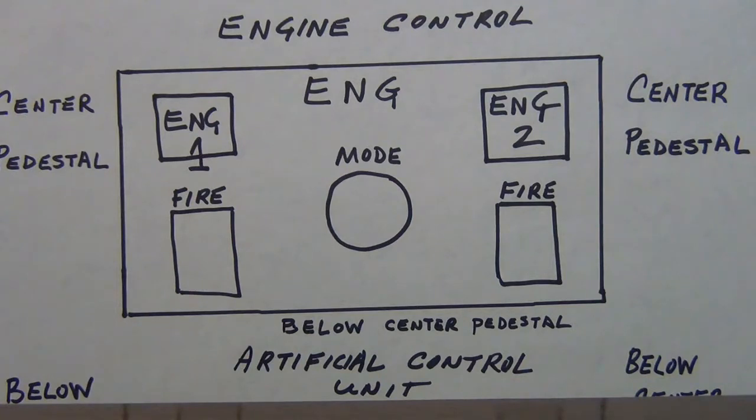And I know that we're not talking about a DC-9, so we're not talking so much about mechanical links and mechanical connections between your thrust control levers and the engines, which you'll have in some of the older models like the DC-9, but you don't have this in Airbus. There's no mechanical connection between the engines and the thrust control levers, just so you know that. Everything's pretty much electronically measured as far as how much input to give to have that thrust for the engines.